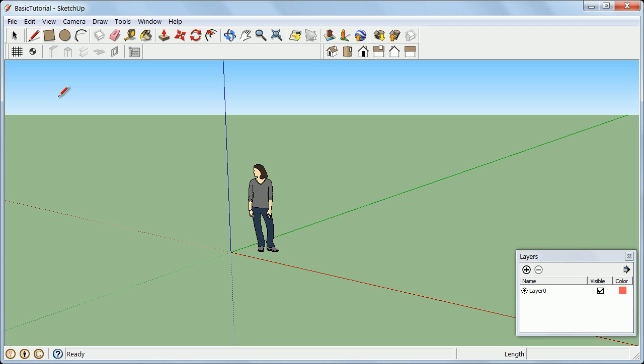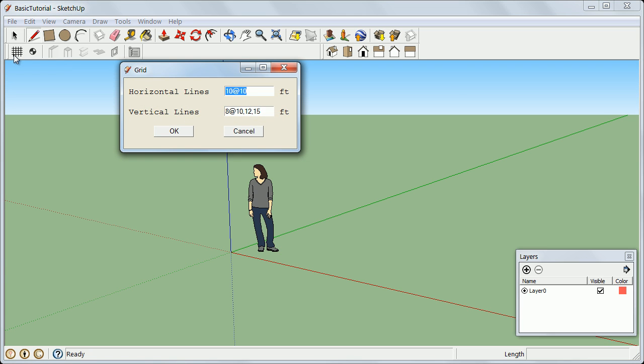The first step in creating a building model is to create grids. The first button on the SketchUpBIM toolbar creates grids. Multiple grid lines are separated by commas. Grid lines can also be defined using the @ sign. A combination of the @ sign and commas is also allowed.